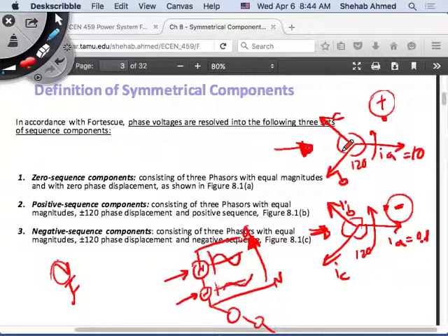So you cannot run machines unbalanced unless you've rated them thermally to make sure that you can tolerate some unbalance, right? That's why, for example, if you get these mobile generators and feed a load, you have to make sure that if it's a three-phase generator, it's going to be feeding a balanced load. Otherwise, you cannot just feed one of the phases only, because it will heat up. It's useless, right? And you're just burning fuel.